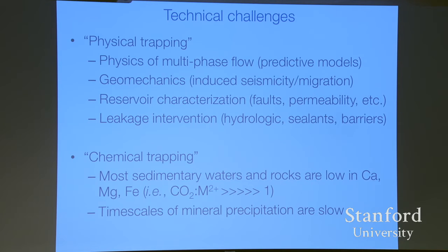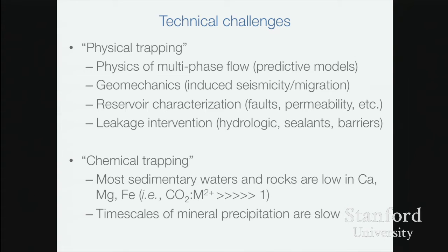And I'll say a little bit about what the technical challenges with CCS are right now. A lot of it relies on physical trapping. We have some understanding of multi-phase flow, but we need a better understanding. A lot of people are working on better models to understand how the CO2 goes in and reacts with the fluids. Geomechanics is a big deal. We've had one CO2 injection site shut down because of induced seismicity and leakage of the CO2. So understanding how the overpressurization that comes from injecting CO2 changes the subsurface is another big area of research.